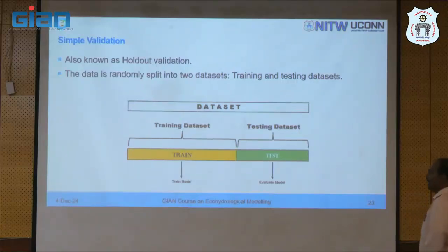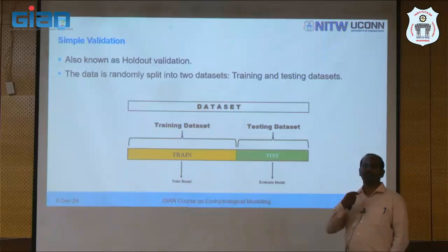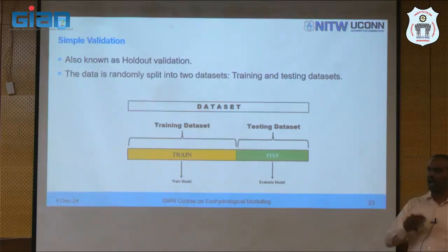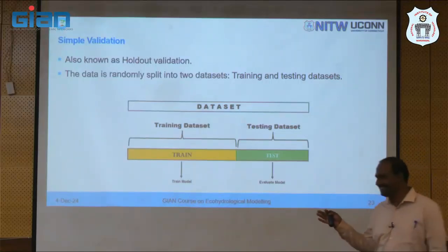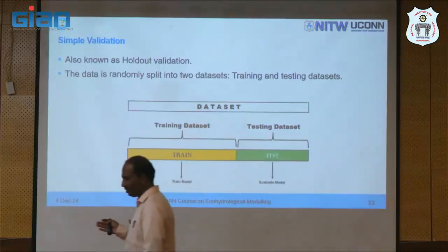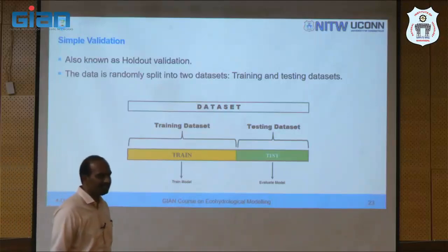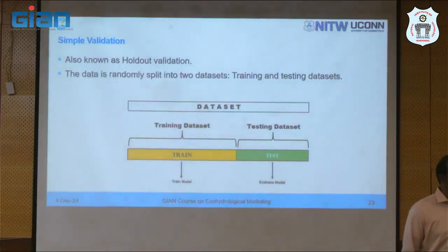So before we do the calibration, we should split the data, check what the precipitation characteristics are, what the stream flow characteristics are, right? How are they matching or not? How many of you have done this? No one? You have not done it. No one, right? And you have set up the models, yes? You never checked whether it should be similar. If it's not matching, then you are not splitting it correctly.